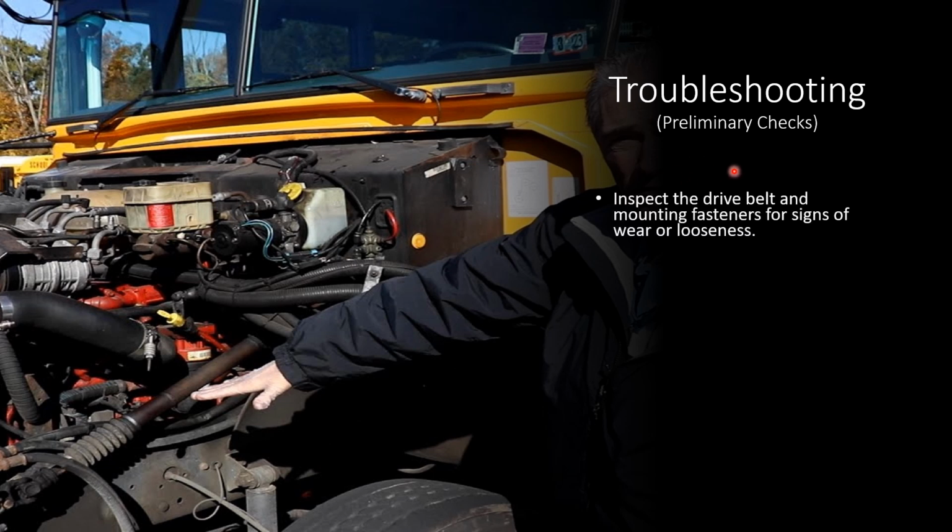I'm going to start by inspecting the drive belt and looking for any signs of looseness, making sure the drive belt itself is not cracked, it's not frayed, that there are not any chunks missing off of the belt. You guys all should know how to do a belt inspection, right? Because the belt is what turns the compressor. It's very important for it to be in good condition so the AC system can work correctly.